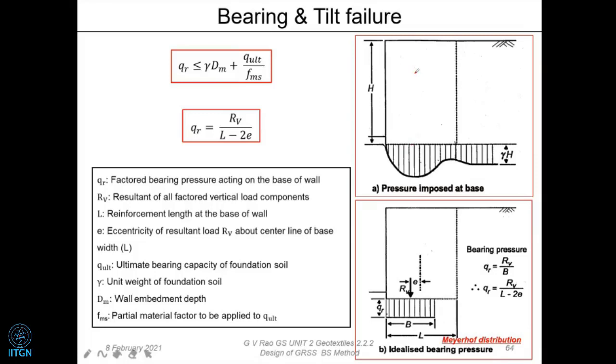We also have to decide what kind of soil we are going to use. We have to pick a soil. Initially, we said it's going to be granular soil, and we have to find out the MDD. So what we know is the MDD and, of course, the angle of friction. For the weight W, which you are going to consider, it is going to be given by the MDD and the size itself.